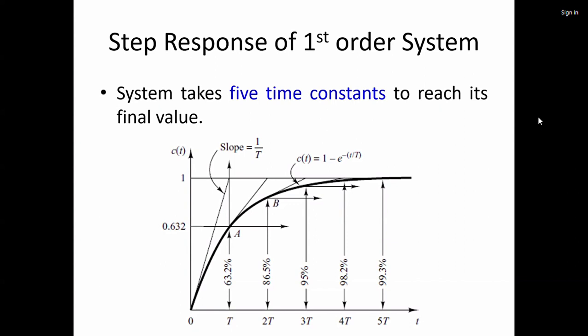The temperature is going to change, but what your thermocouple is going to measure is voltage, as output, because of the Seebeck effect. Now the question is, how long should you wait before you actually record the data? Your system should have reached the steady state.